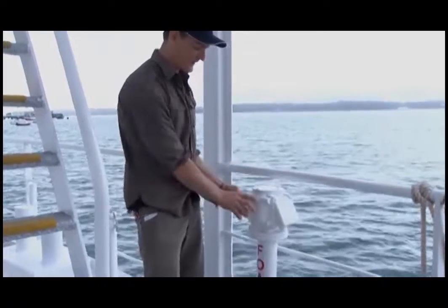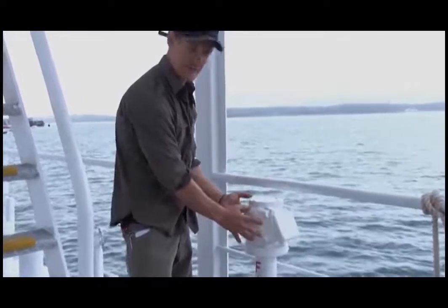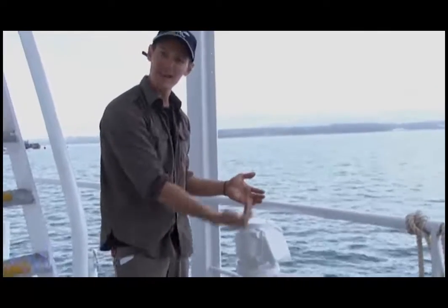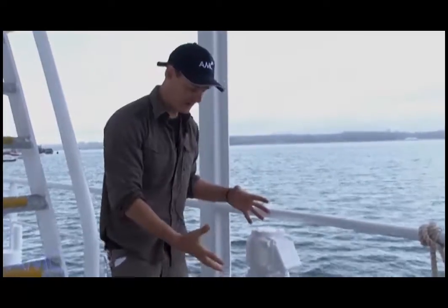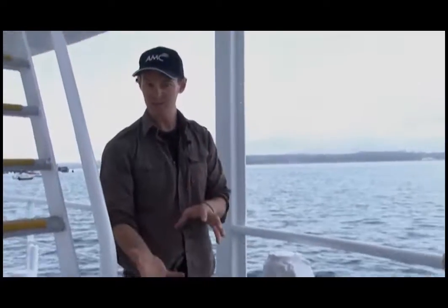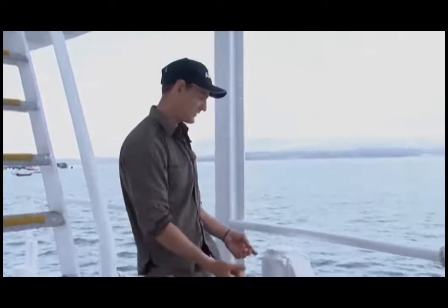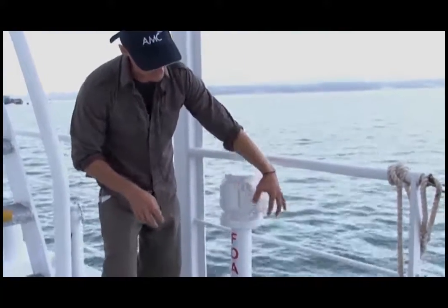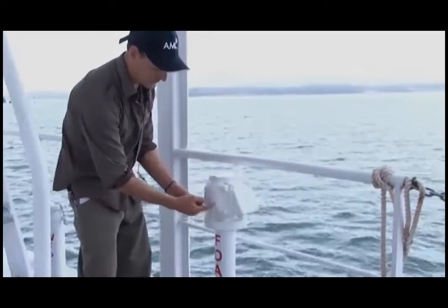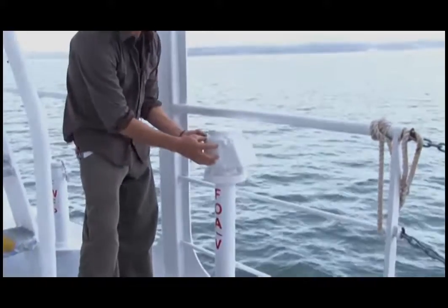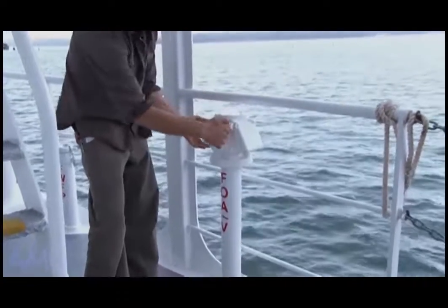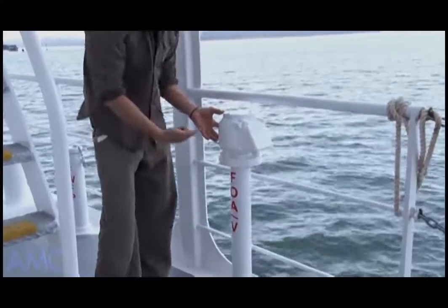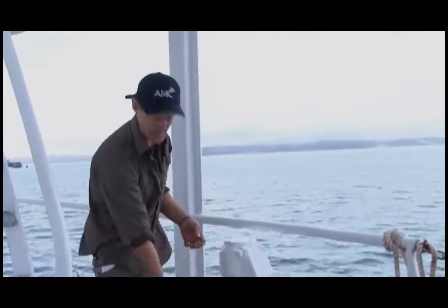We also have another feature of this breather, and that is we need to allow air to pass in and out depending on the state of the tank, but we want to prevent seawater from getting in also. So to prevent that, we've got a downward facing shield, but we've also got a ball that acts as a float in here. So if any water does get in for whatever reason, it floats the ball and stops the seal and won't allow any water or liquid to travel into the tank.